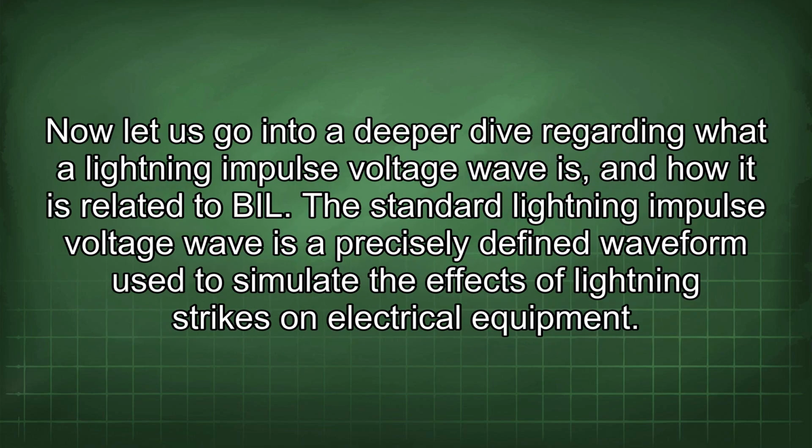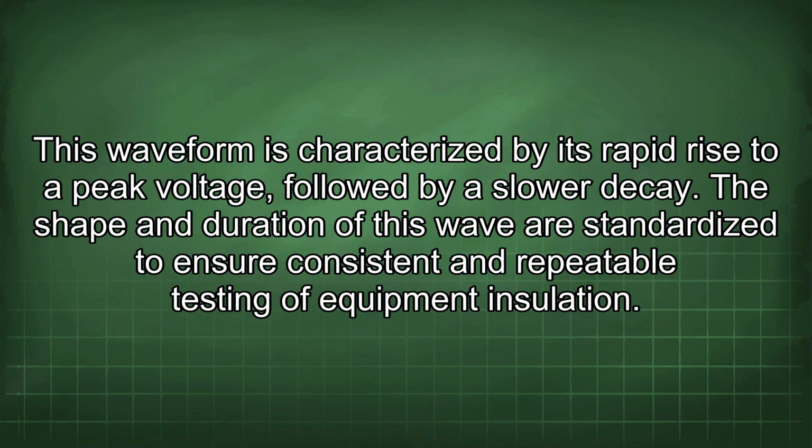Now let us go into a deeper dive regarding what a lightning impulse voltage wave is and how it is related to BIL. The standard lightning impulse voltage wave is a precisely defined waveform used to simulate the effects of lightning strikes on electrical equipment. This waveform is characterized by its rapid rise to a peak voltage followed by a slower decay. The shape and duration of this wave are standardized to ensure consistent and repeatable testing of equipment insulation.